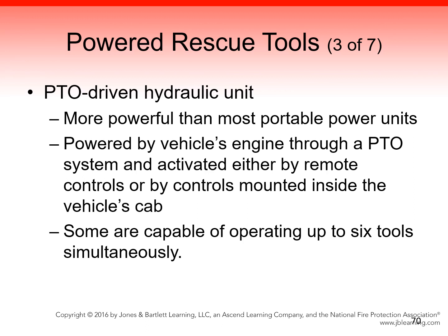Some are capable of operating up to 6 tools simultaneously. The driver operator must be aware of the limitations of the equipment on his or her apparatus. Do not attach and operate more tools than the manufacturer recommends, as this may damage the equipment and delay the response operation. A positive displacement pump is used to pressurize the hydraulic fluid in the system.